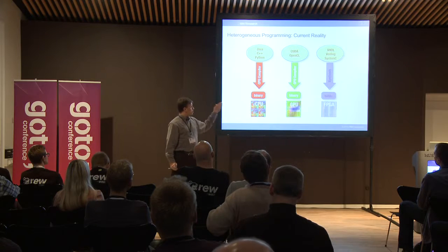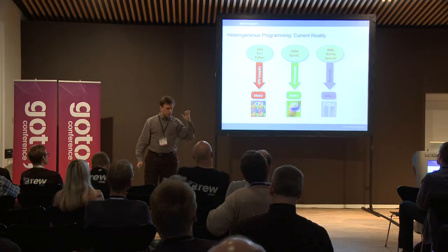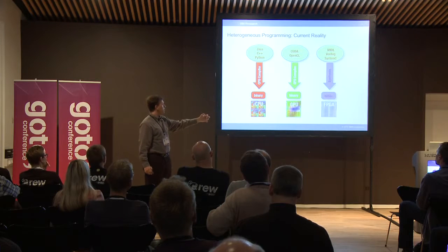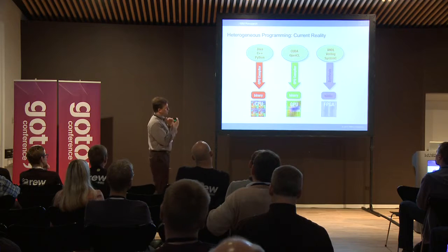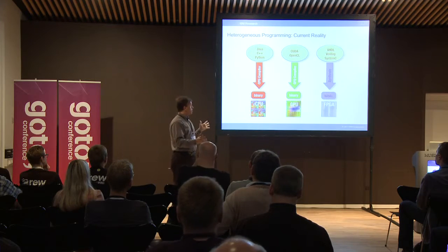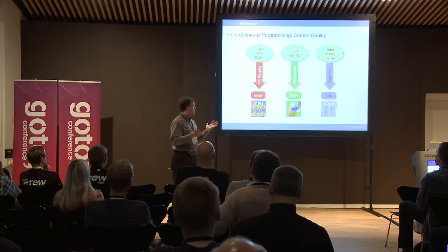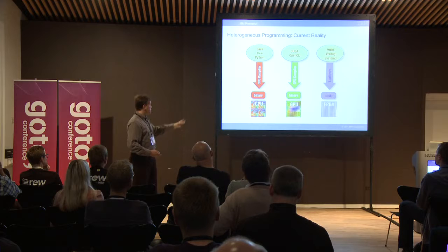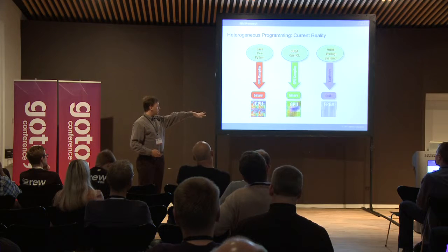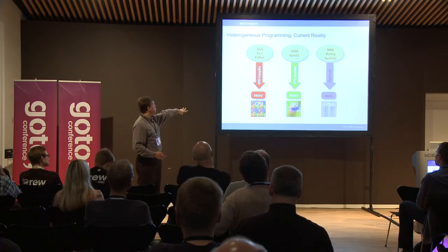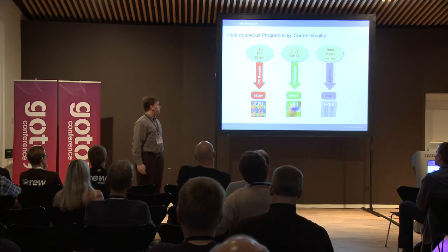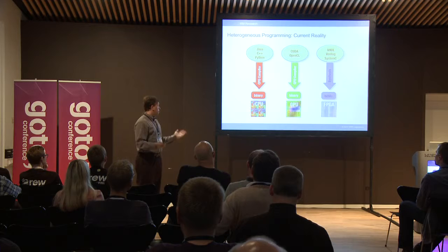These are extremely low-level, basically circuit design languages that describe your computation. You don't have any benefits on the FPGA of an operating system or device drivers or memory managers or any of the things we expect, the system software which makes writing programs easy. So it's really a very low level, very painful experience compared to writing software to be able to use an FPGA in a heterogeneous system.